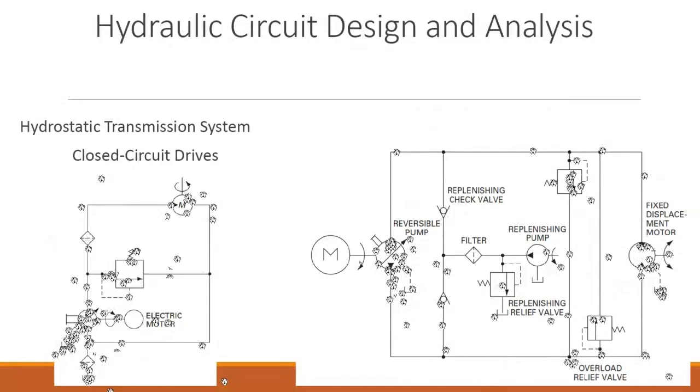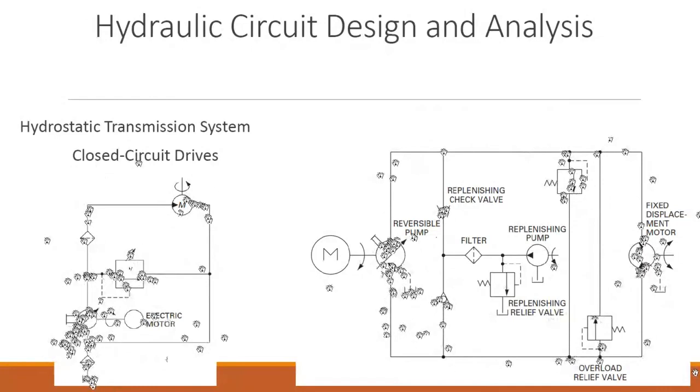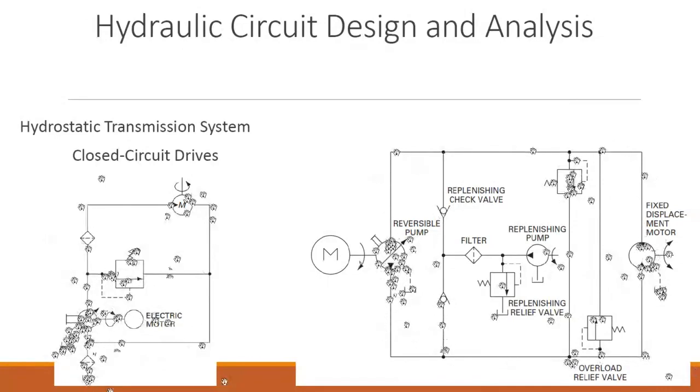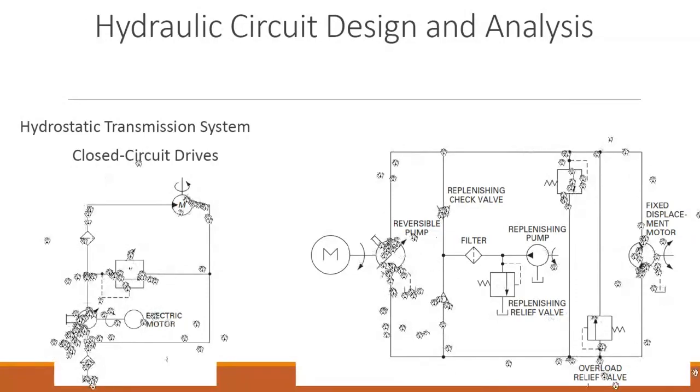So in this case, we see that these two check valves and this line are not being used, right? In the regular and normal operation, this whole line is not used because the oil comes here, there is nothing, or just goes there, circulates, and does the work. And even this one. So these two are overload relief valves. See the point, overload. Why? This is what I said.